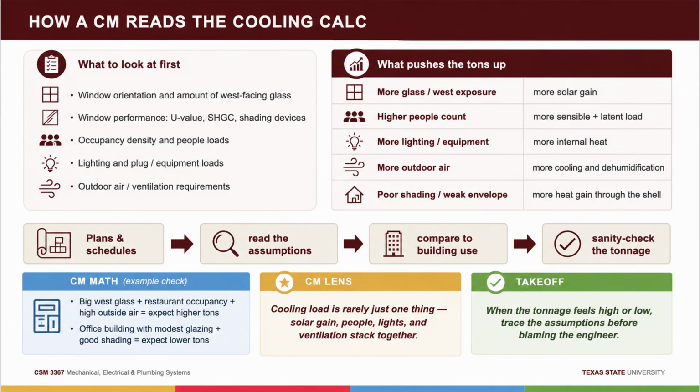Mechanical is routinely one of the largest trade packages on a commercial building, and its cost tracks tonnage. The rule of thumb plus a dollars per ton figure lets you gut check a mechanical budget or a sub's bid in about 90 seconds. If the office building should be around 115 tons and the low mechanical bid only makes sense at 80, somebody missed scope, and you just caught it before it became your problem in month 9.